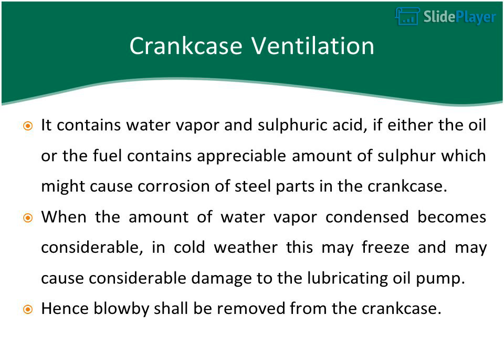Crankcase ventilation. Blowby contains water vapor and sulfuric acid if either the oil or the fuel contains an appreciable amount of sulfur, which might cause corrosion of steel parts in the crankcase. When the amount of water vapor condensed becomes considerable, in cold weather it may freeze and may cause considerable damage to the lubricating oil pump. Hence blowby shall be removed from the crankcase.